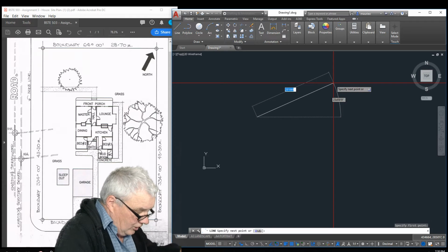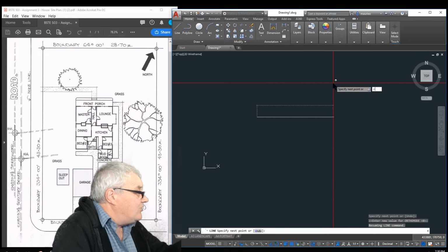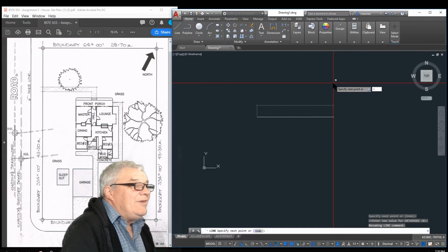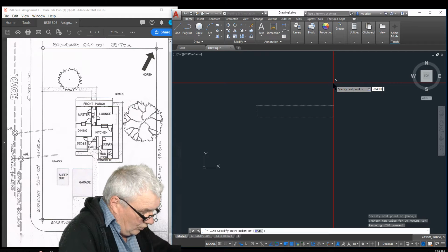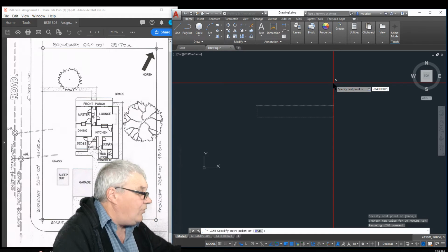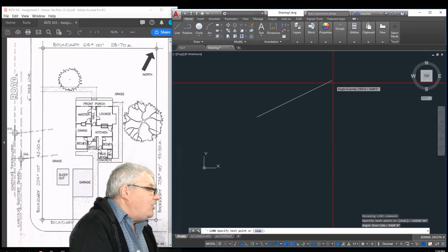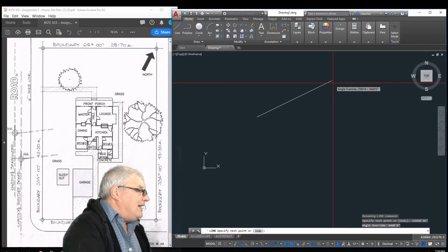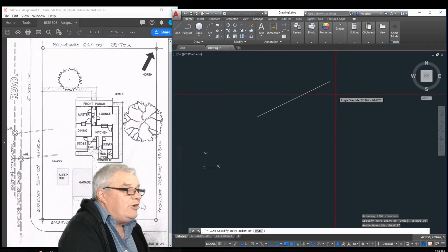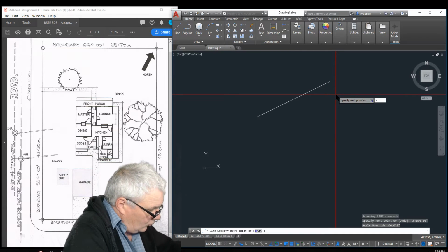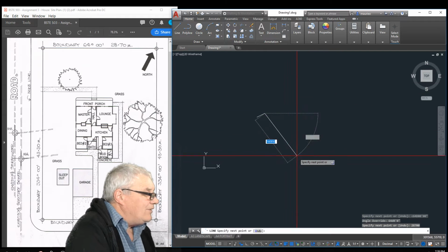What I do is go shift and the less than symbol, which shows up there, and then I just go 64 degrees, 00 minutes, 00 seconds, if I had degrees, minutes, seconds. I don't in this case. And now I'm going to push enter, and make sure you get that angle override situation. And there it is, there's your 64, and all you need now is the length, 28700 millimeters, and that's that one there.